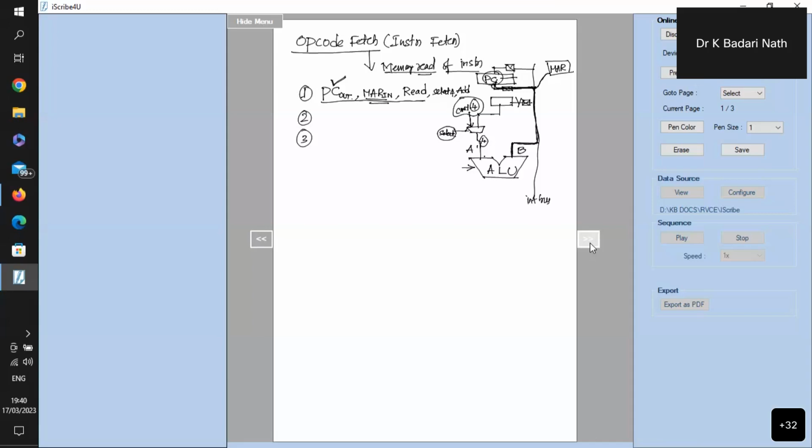The B input of the ALU is always connected to the bus; there are no switches there. So the PC is available as the B operand, and I am pushing the 4 into the other place, the A operand of the ALU. Now everything is there, and the add command is also given. In a single clock cycle, the addition can be performed.